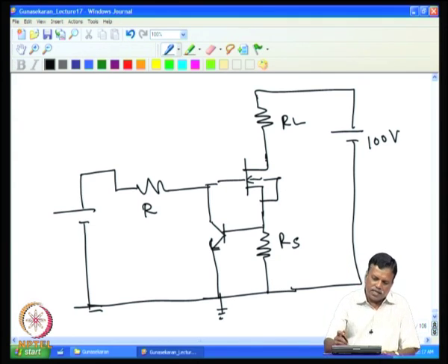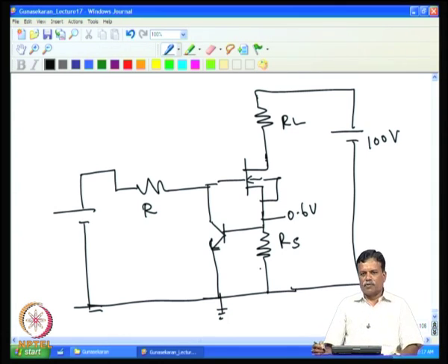In this case, if the short occurs, then the current will go high in this, that will increase the voltage at this point. Then immediately this transistor will conduct, and then more current will flow through this, and that will make the voltage at this point reduce, and that will reduce the current. So, eventually the voltage at this point will be limited to 0.6 volt. So, 0.6 divided by this resistance will be the current that will be flowing. Now, we are trying to remove the power dissipation in this, because if I put 1 ohm, then as we said, the current is 0.6 ampere only, and it cannot go more than that.